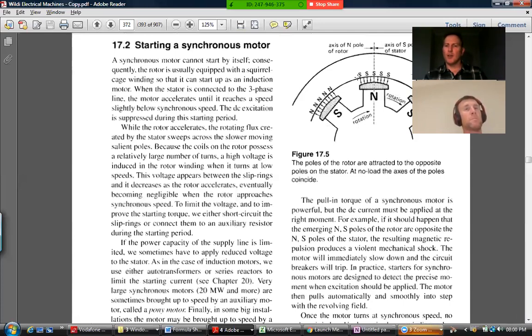Otherwise, for a big machine, you can choose whether one wants an extra motor or to have extra windings in the same motor. If you have the luxury of a speed controller, a variable speed drive, you can take the 50 hertz and slow it right down to 0 hertz and slowly crank it up, so that this thing starts to slowly spin faster and faster. So if you have control over the frequency by a variable frequency drive, then you can start pretty much at 0 and slowly crank this thing up.